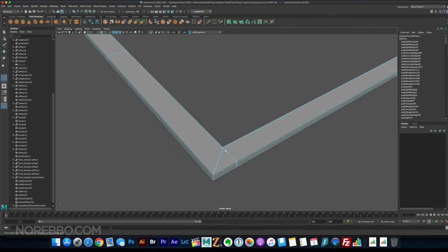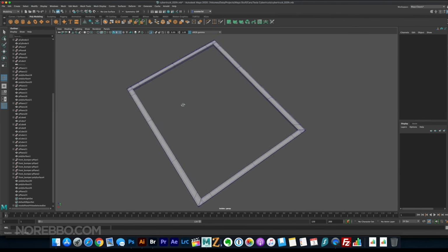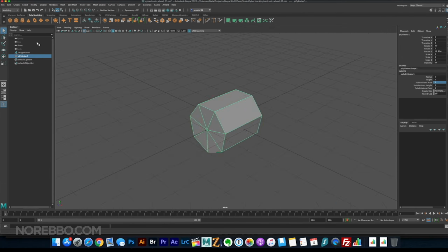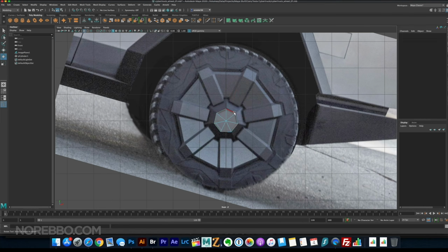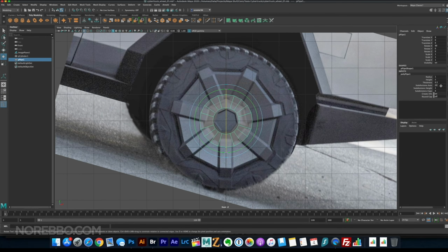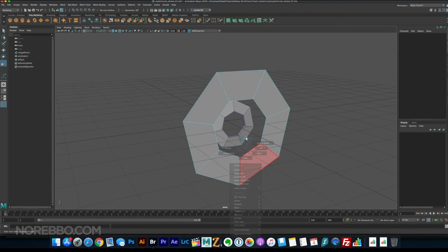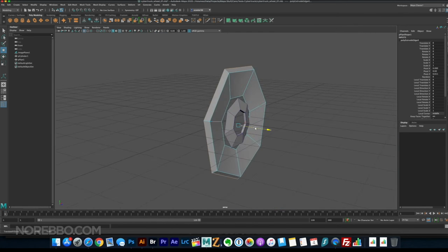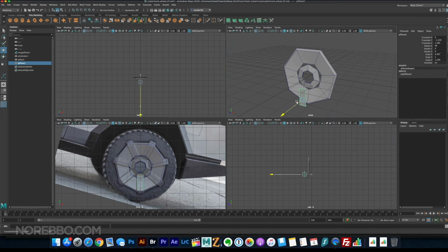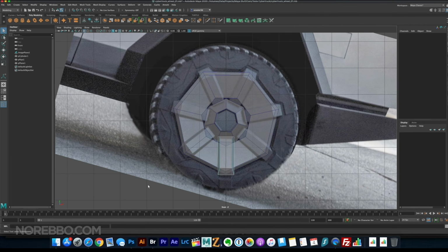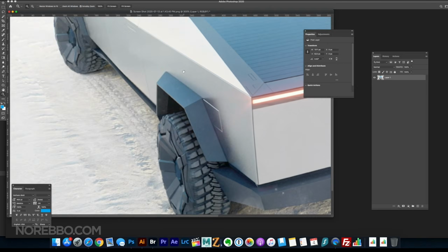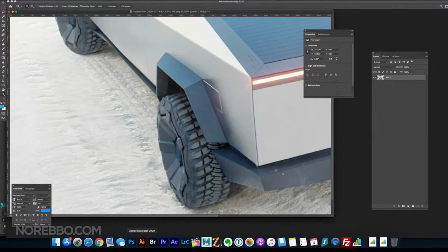And then this piece right here. This is the trim piece that goes around the rear cargo cover. And that cargo cover itself, I didn't record the entire process. I spent probably an hour and a half trying to figure out how to model those grooves in that panel. You think it's so simple, but it's not. And long story short, I just had to extrude edges vertically and then horizontally, and it was a lot more of a problem than I thought it was going to be.